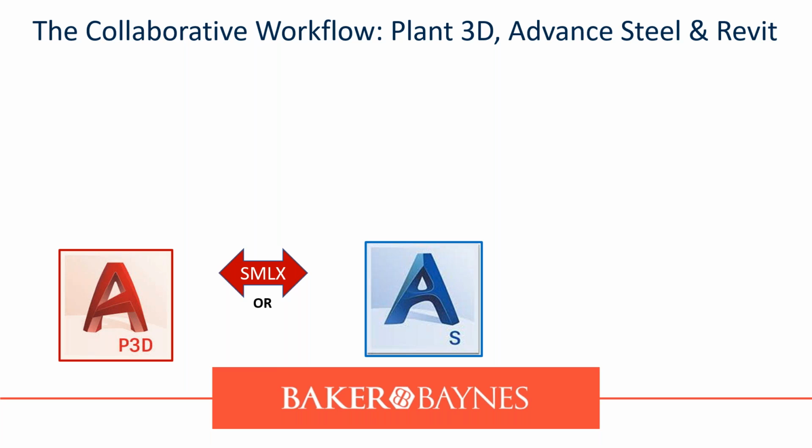The second way that is also pretty good is by adding your Advanced Steel model in the location of the project file that you would need to set up in Plant 3D. So Plant 3D, when you're creating a project, I'm not a Plant 3D specialist, but I do know more or less how it works. You had to create a project, set a project file path. Once you've done that, you can create subfolders. So for example, I would create a folder for Advanced Steel or steel structure, and I would drop in my Advanced Steel model in that folder.